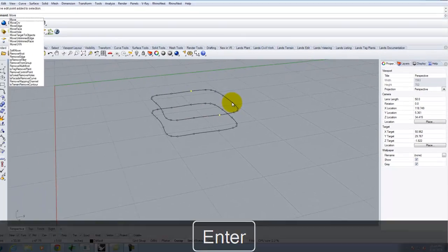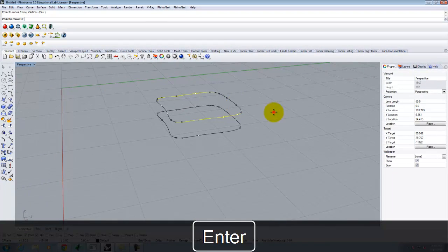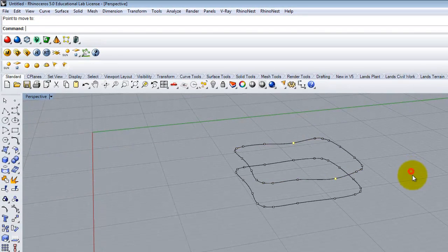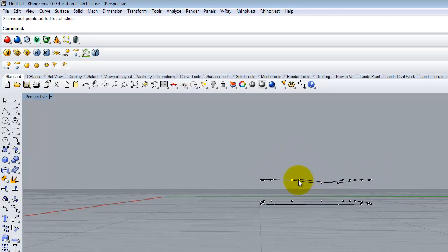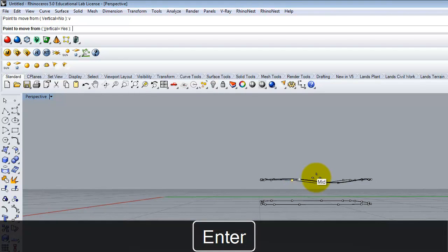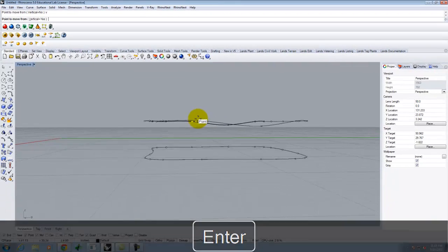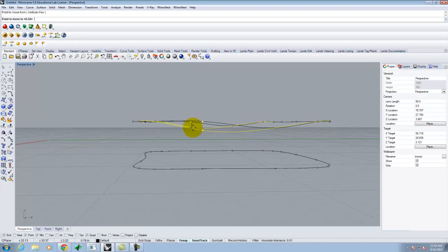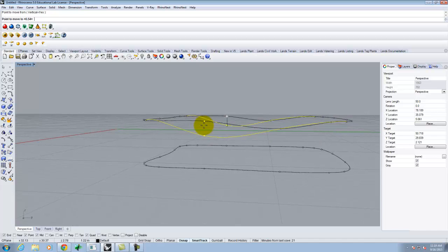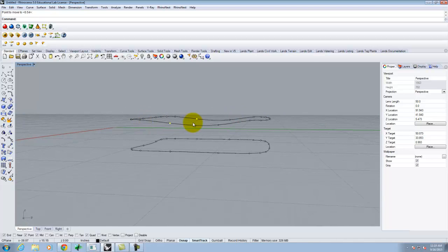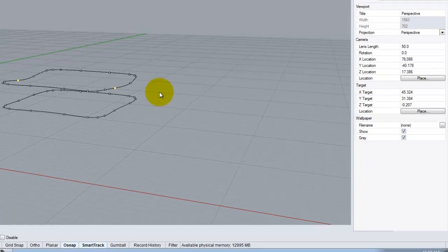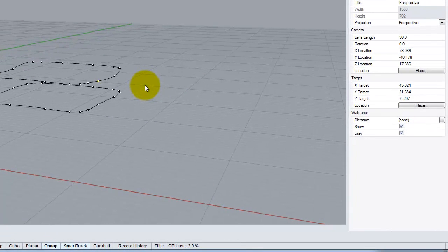So let me go ahead and go to Move, V for vertical, and I'm going to push these down a little bit there. And so you can see in the side view, there's a little bit of a depression there. Right, let's move these down a little bit too. Move, vertical. Again, gumball, good opportunity here if you want to use the gumball. Right. Part of the reason the gumballs work nicely is because we don't need to snap to anything. Right? It's just an arbitrary nudge.